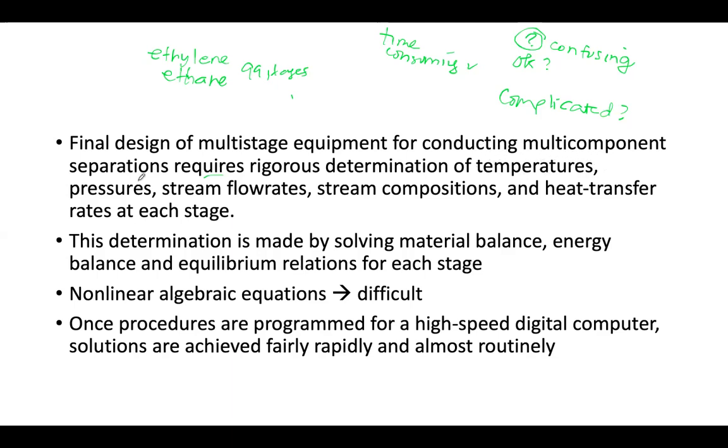And the pressure may also change. We assume that the pressure is the same, but we know from fluid mechanics that there are pressure drops. And also the streams: what happens if we have multiple streams, side streams, and how to measure the stream composition and the heat transfer rate at each stage. So it is very difficult, but it has to be done, and chemical engineers have done that all over the world.